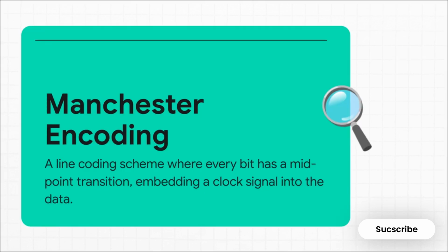For wired connections, one of the classic solutions is called Manchester encoding, and it solves a really tricky problem: timing. I mean, if you just send a long stream of ones and zeros, how does the computer on the other end know where one bit stops and the next one starts? Well, here's the brilliant trick. Manchester encoding forces the electrical voltage to change right in the middle of every single bit. That constant transition works like a metronome, a heartbeat, embedding the clock signal right into the data itself to keep everything perfectly in sync. It's so clever.